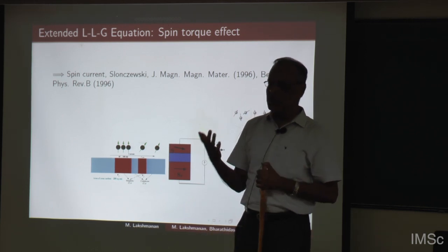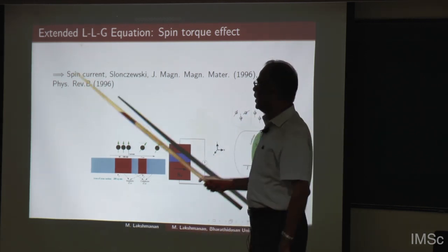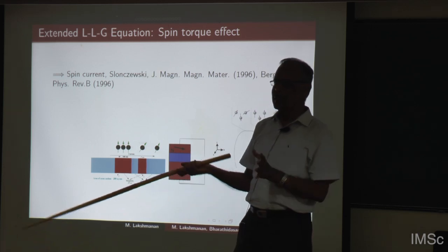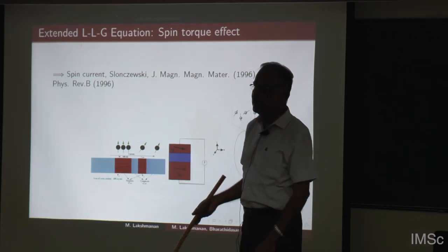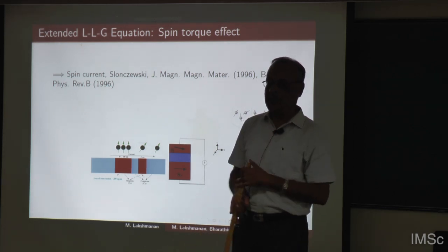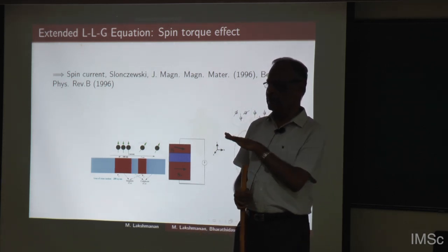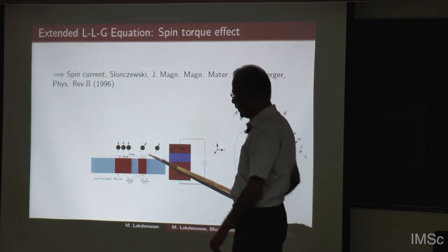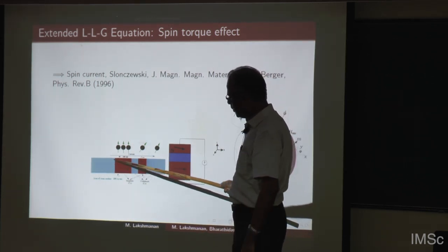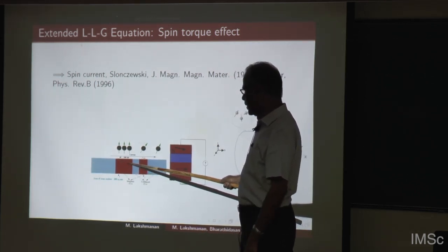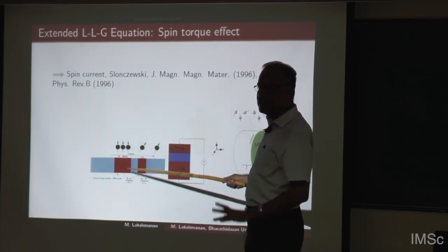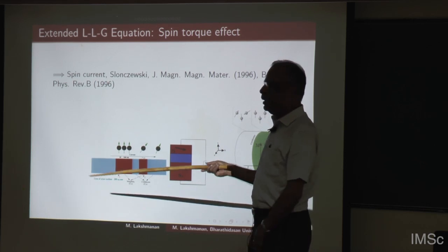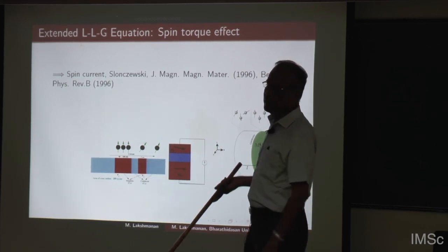So, this you can show quantum mechanically. Semi-classically, Slonczewski had shown by considering this as a five-piece one-dimensional material. You look at the WKB wave function of these five pieces. The outer two are not important. What you are interested in is the spins that pass through this layer and then this layer, and see how they are interrelated, the influx and the outflux.